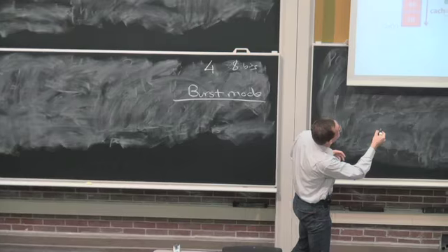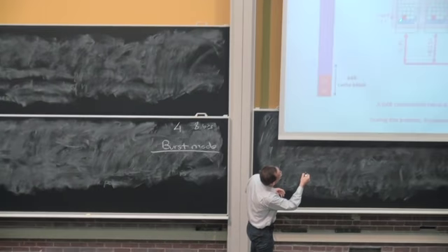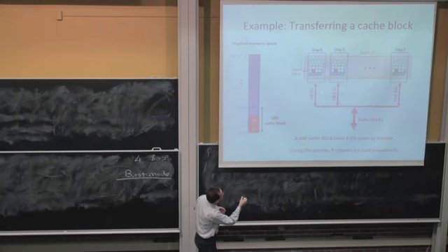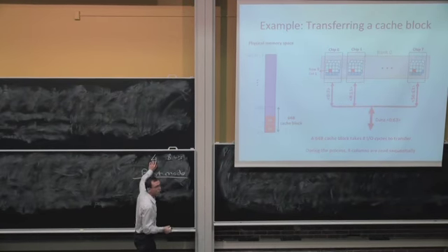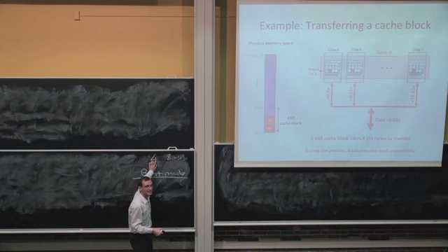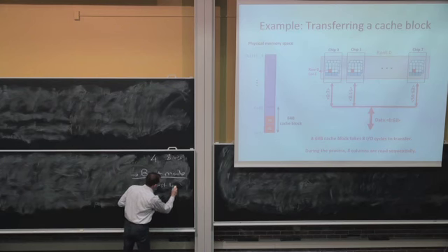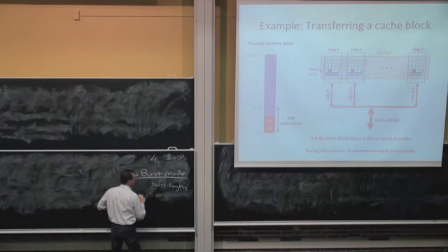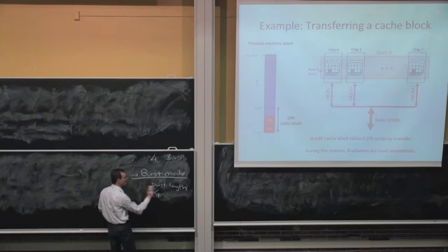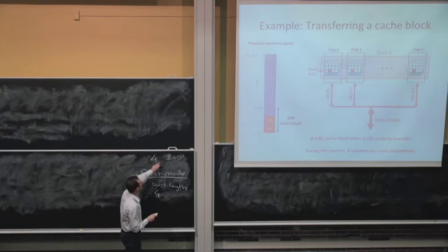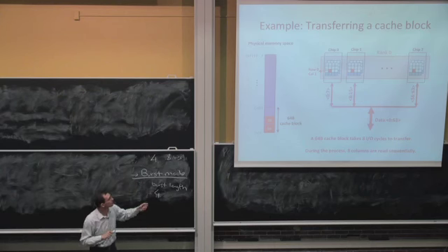Basically, instead of providing only one of the 8 bits, you can tell the DRAM chip to provide 4 of these in consecutive cycles. And what the DRAM chip does in this burst mode is you specify the burst length. The memory controller says burst length is 4, which means that whenever the memory controller requests something, the DRAM chip in consecutive cycles puts out 4 8-bit values.